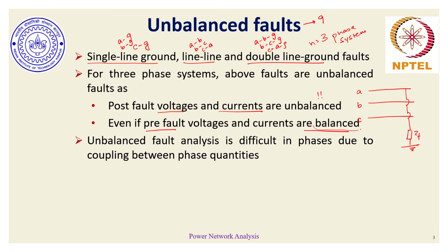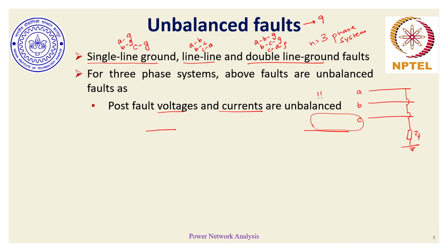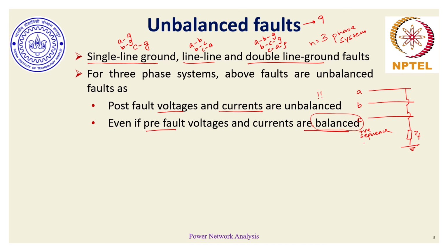So positive sequence voltage is one such notion of a balanced system. By balanced, I mean specifically that the corresponding phasors that existed in the network before the fault occurred pertain to positive sequence voltages or currents, in which all three phase voltages have equal magnitude and are 120 degrees spaced apart with positive sequence orientation.